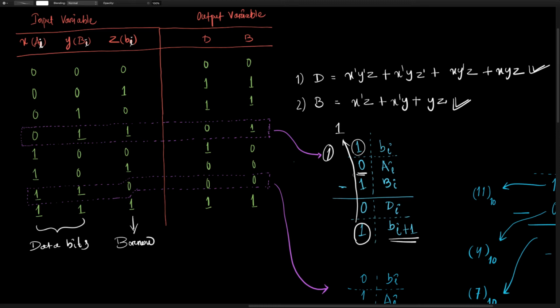Now what about this bit calculation? As 1 was taken as a borrow from its previous stages, there is no 0, there would be 10. But as its previous stage has requested a borrow from 10, 1 would be transferred to that, and here remains not 0, here remains 1. So 1 minus 1 goes 0. So that is the difference. But as a borrow was requested, 1 would be a borrow for this stage, which would be transferred to the previous stage, which will tell us that a borrow was requested by this particular stage.